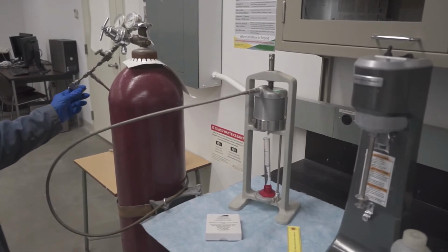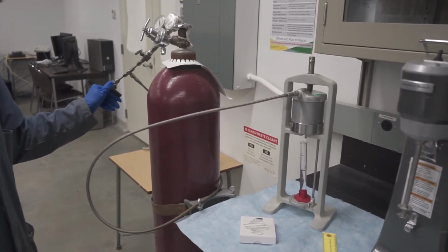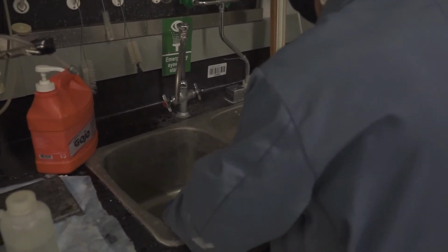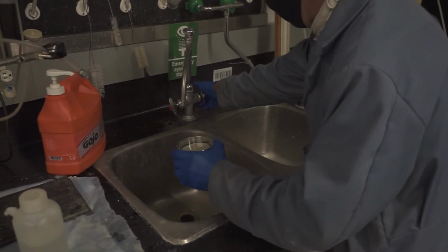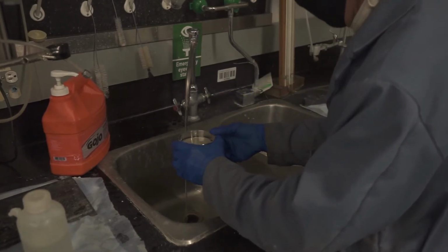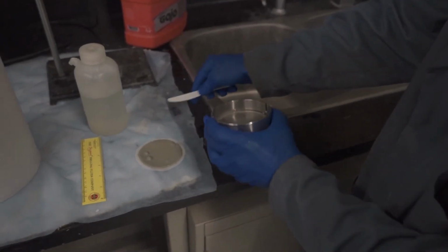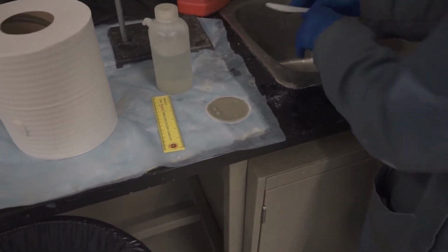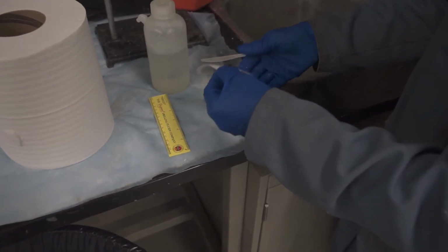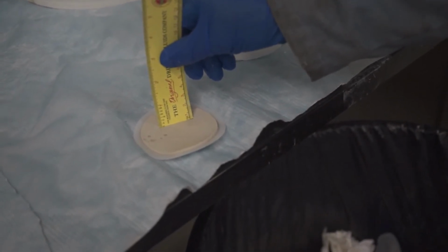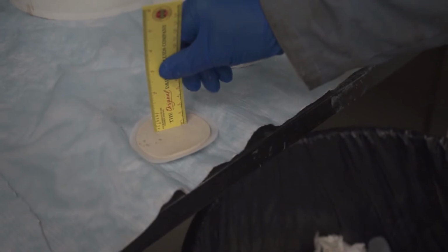Release the pressure which is being applied on the test cell by opening the relief valve. When the pressure is released, open the top cap and discard the remaining fluids from the cell. Now remove the mud cake from the bottom of the test cell, and after a short rinsing, measure the cake thickness. Filter cake thickness is measured in units of 1/32 of an inch.